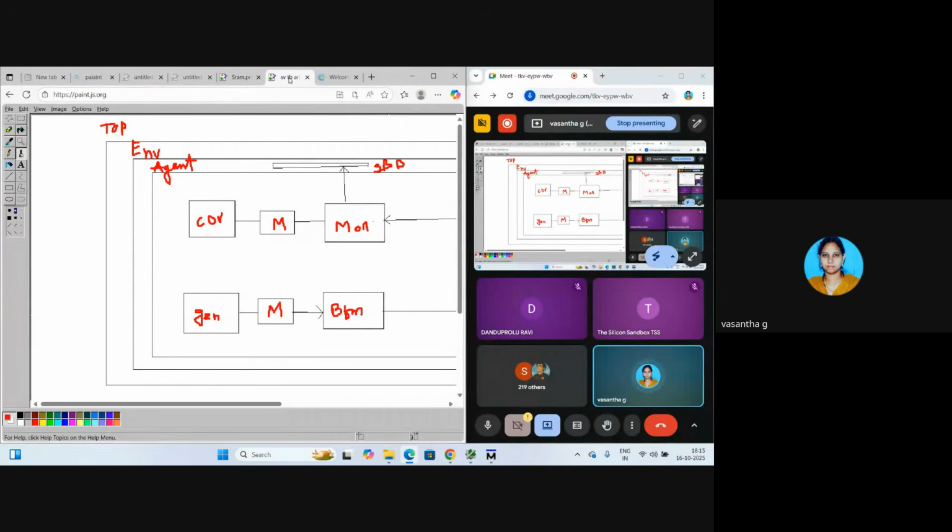So why do we need SystemVerilog? Already we discussed everything in Verilog, right? There are 4-state and 2-state variables. These state values are only for simulation purposes, which we learned in the introduction of Verilog. So what are the state values? 0, 1, X and Z, right? Unknown and high impedance, so logic 1, logic 0. That is the reason these are the values.